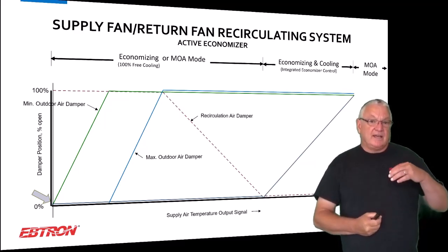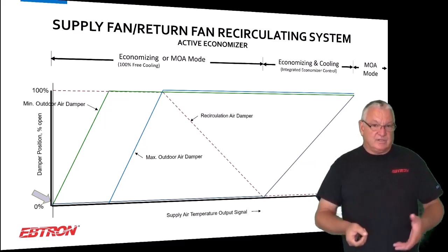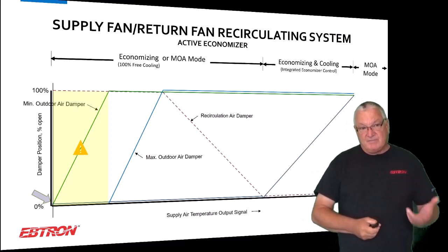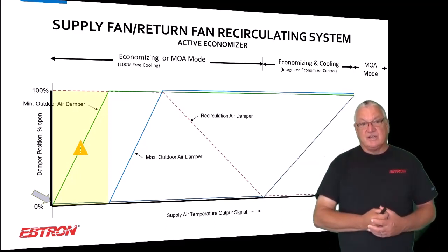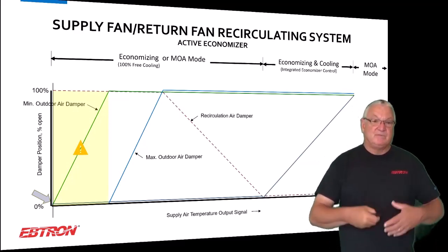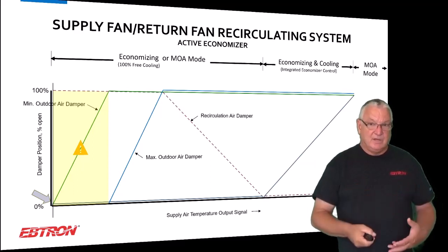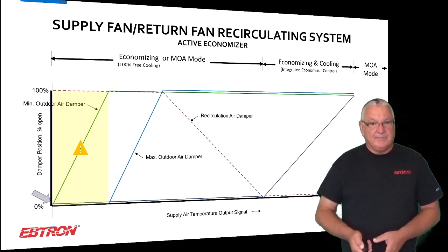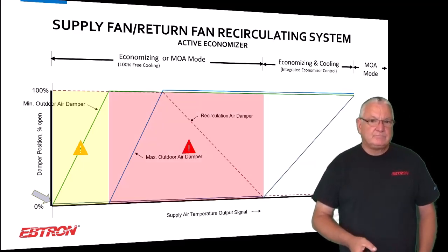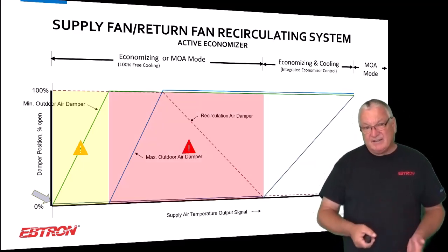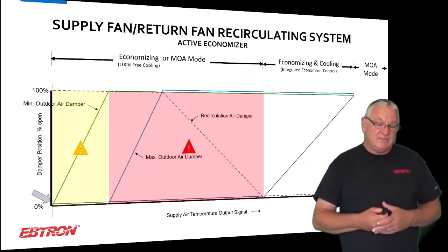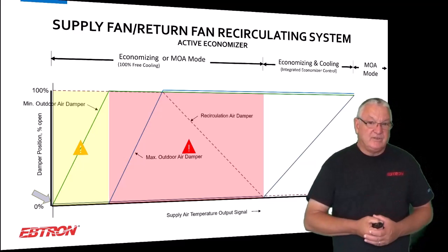You're going to get to some pretty low flows where just a little bit of wind could be a problem. So anyhow, you just have to make sure that when you're in this yellow range, you're looking and see that you don't fall below the minimum, because if you do fall below the minimum, you've got to shift back to minimum outside air mode. And if you're in this area doing the sequencing the way I want, I don't know that you always really know the outside airflow rate.